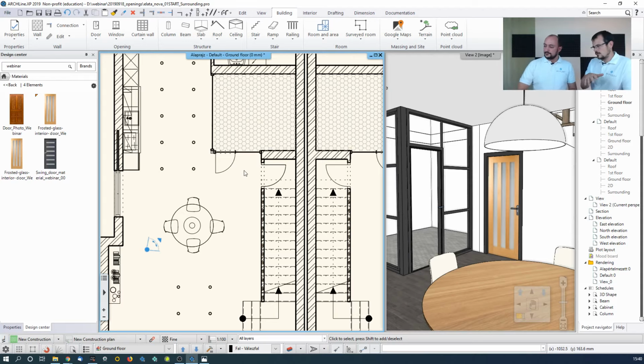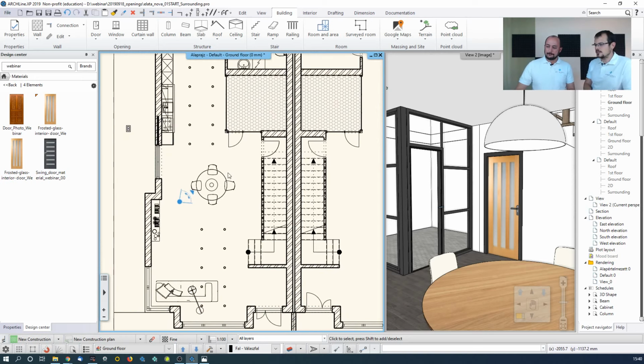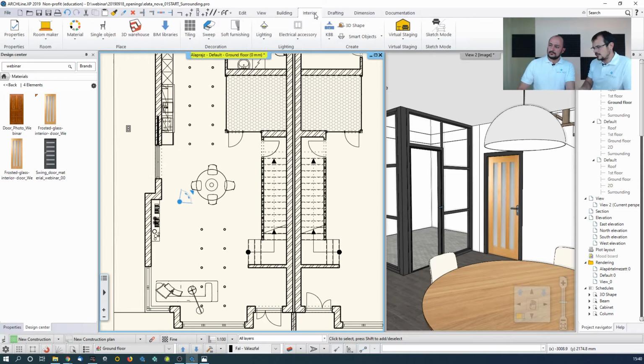Just a recap before we move on to other topics that we want to discuss, being the curtain walls and the corner windows. What are the sources for creating a new door? We used an image. We used measurement data, and that's how we created the one with the door wizard. And we used external objects, which could be SKP, OBJ perhaps, RFA, so anything that comes as an object, as a 3D body, can be turned into a door and window.